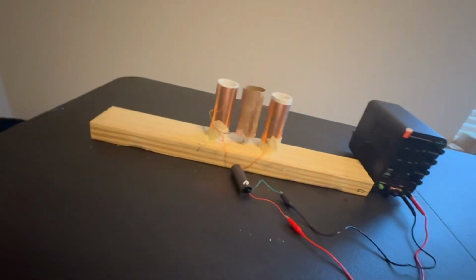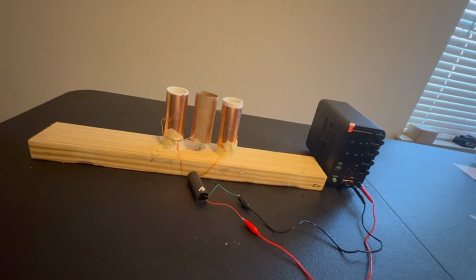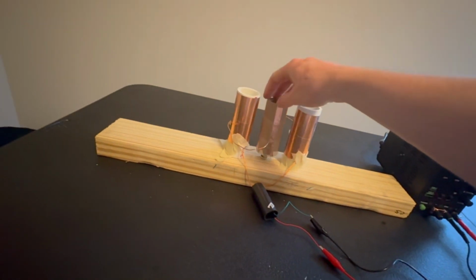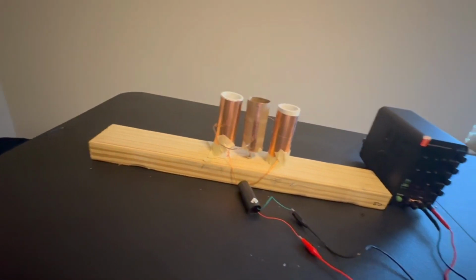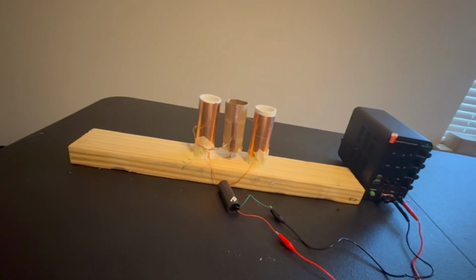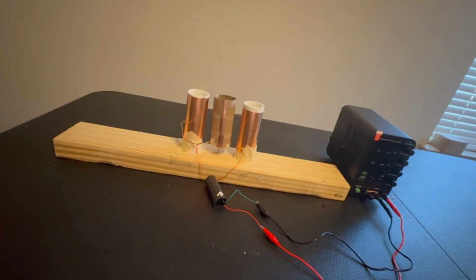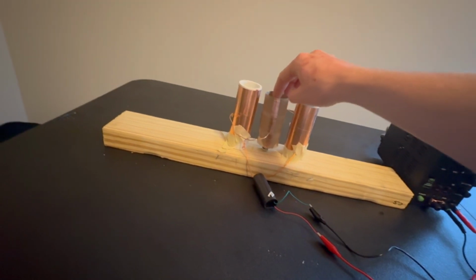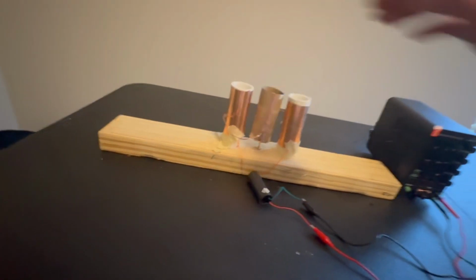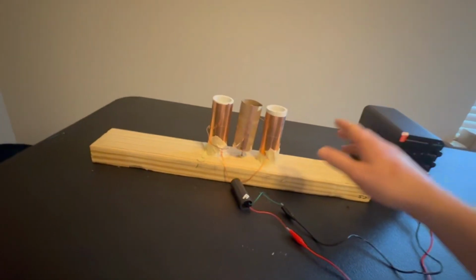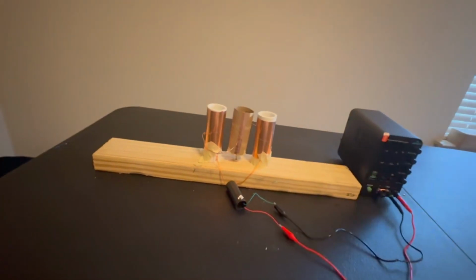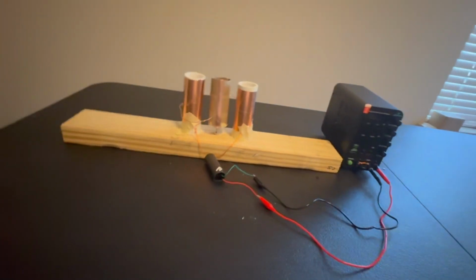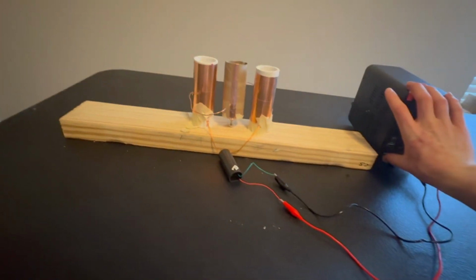As you can see, it spins quite freely. Now, when the rotor blade is by the positive stator here, it is charged, and because like charges repel, this buildup of charges starts to rotate the rotor. And once it comes to the grounded side, it starts to discharge, which then continues the cycle. Now let's see it run.